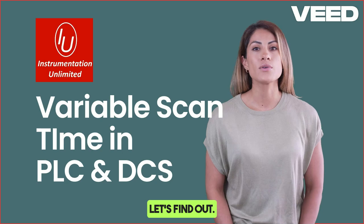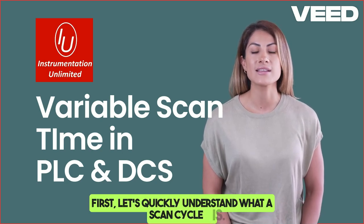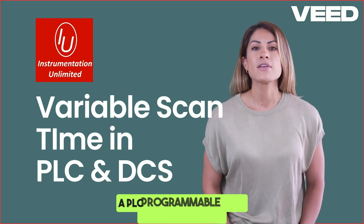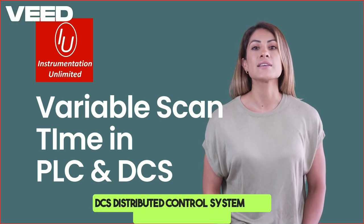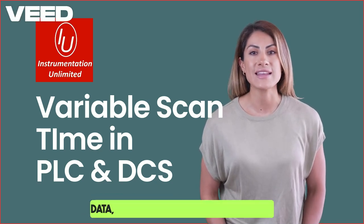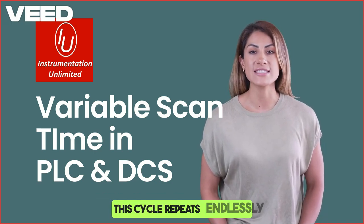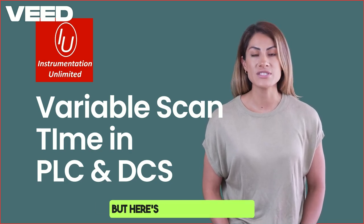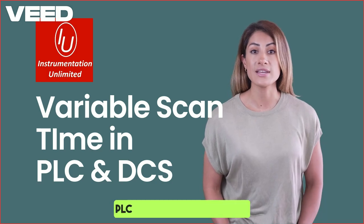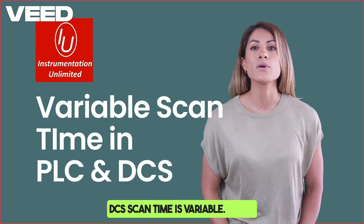Let's find out. First, let's quickly understand what a scan cycle is. A PLC, programmable logic controller, and a DCS, distributed control system, both continuously scan data, process logic, and send outputs. This cycle repeats endlessly to control industrial processes. But here's the key difference. PLC scan time is fixed, while DCS scan time is variable.